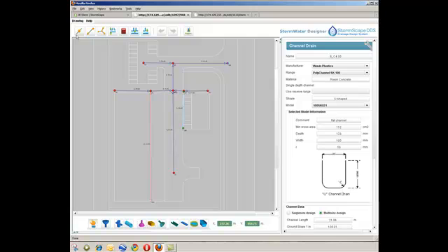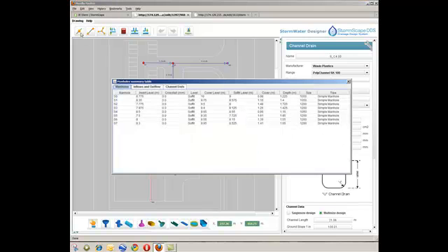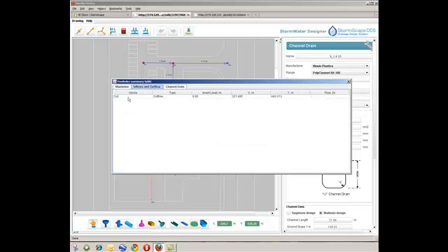The associated calculation tabs are located in the top left corner, directly above the design window, and the first one selected provides the manhole summary table. This table outlines the physical properties of the manholes included in the system design, and incorporates the respective levels and sizes of the chambers in question. The second tab in this table provides details of system inflows and outflows, recording the level and location of the single outflow in this case. The third tab details similar information in respect of channel ends.